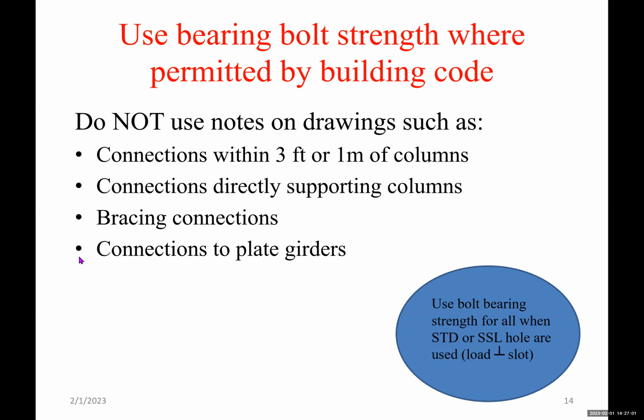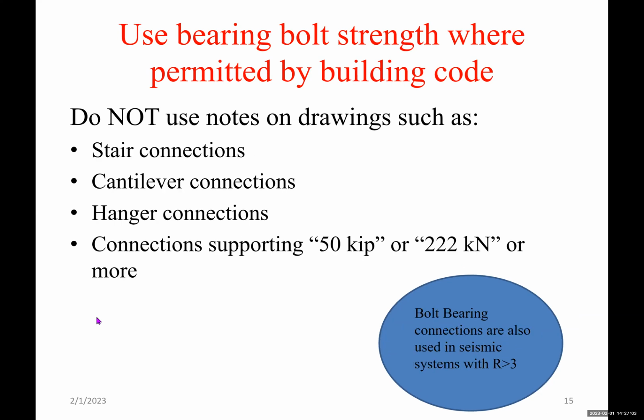Do not use notes on the drawing such as stair connections, cantilever connections, angle connections, connections supporting 50 kips or equivalent in metric 222 kilonewton or more. Okay, do not use that. As I said, treat each connection the way it is.